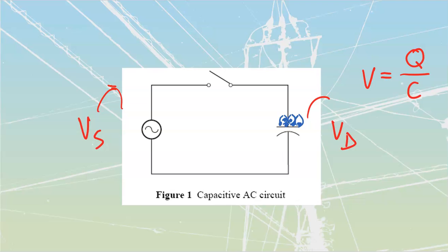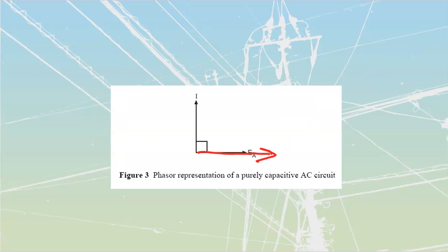Like we did for the inductors, we're going to use this form of opposition that we are going to call our XC. This is going to be my capacitive reactance. It's going to be the same as ohms in that it's going to oppose the flow of current, and it's also going to utilize the ohm symbol in all of my measurements. This XC is going to be affected the exact same way that my inductance is. Remember, these are just flip sides of the same coin. Frequency and the physical value.